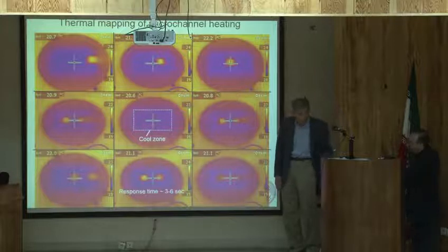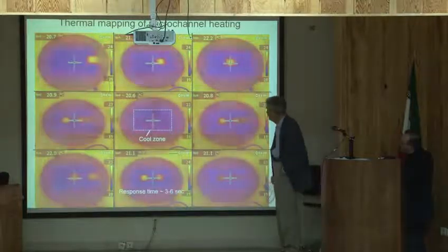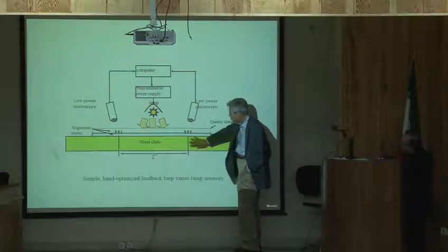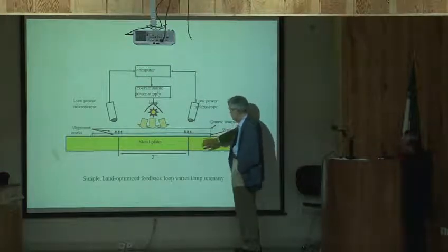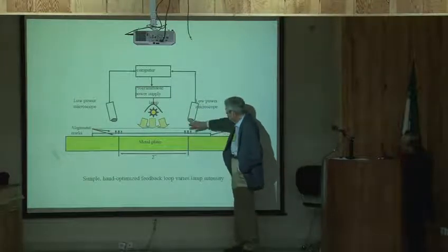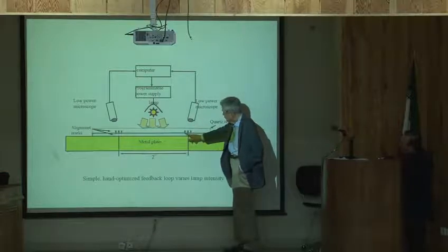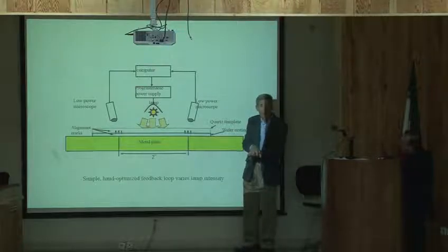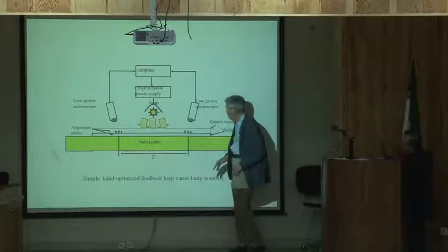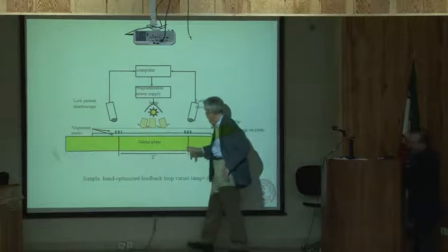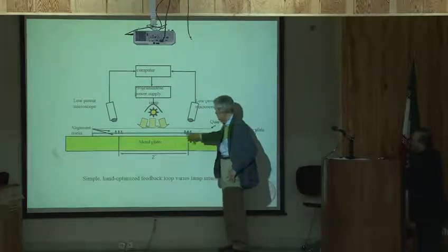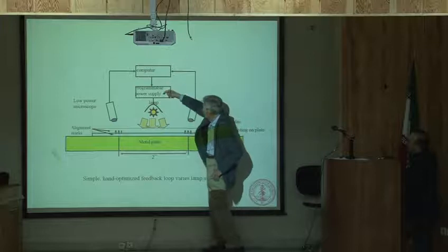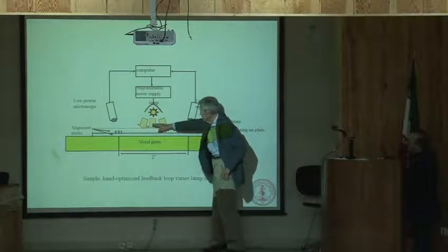So the very first experiment we did didn't even use the microchannel heatsink. We just used a metal plate initially because I was having trouble with my plumbing. And Dr. Moon has a technique for using quite inexpensive microscopes for sensing the overlay between two gratings. He claims he can get an accuracy of less than half a nanometer. So initially our project was to see how well we could stabilize the dimensions, the overlay over this area, simply with two sensors, going into a computer, and then into a programmable power supply, which controls the lamp that controls the heat here.